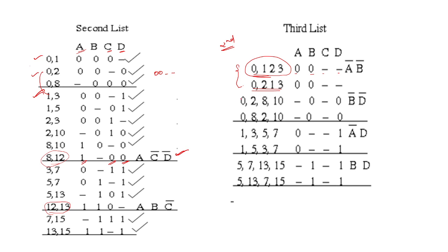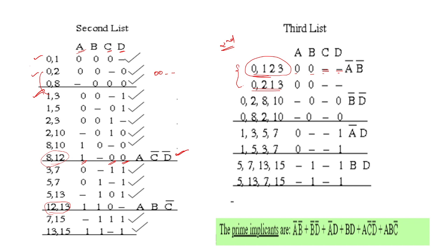And next again we have to check for the groupings if the two dash is common. So these two are considered as a 1, and if there is a 2 dash common in the same position, and again 1 bit change, we are having a third reduction. So that is not possible here. So we are having these all the minterms.